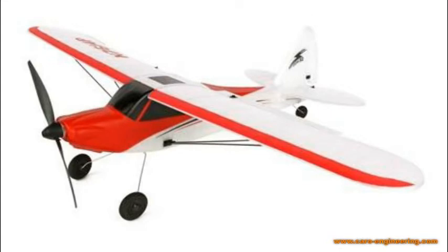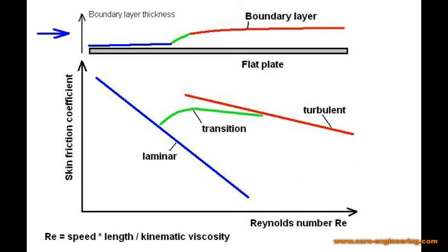The flow behaves differently. What this means in a more scientific way is that the friction, or the losses due to air particles sticking to the skin, change with the length of the object. To illustrate this, let's look at airflow blowing over a flat surface at constant speed, so that all the drag is purely friction and there is no form drag. At the leading edge of this flat plate, the air still has its full speed and the energy loss of the particles is high, which means the skin friction coefficient is high.